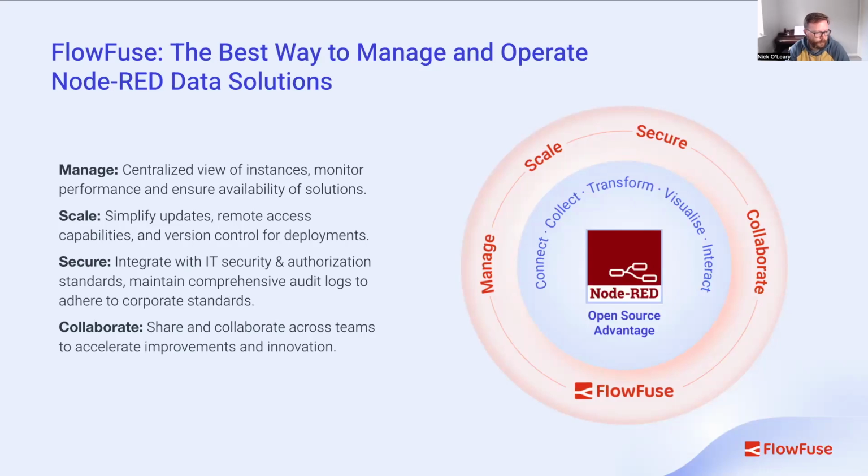A question from Trent Christopher for you, Kurt, possibly. Does Node-RED integrate with special I/O as well as just digital I/O on the rack? And what about remote I/O? He assumes this would have to be handled in CODESYS. Is that one you can speak to? For remote I/O, we would use Modbus remote I/O, like a 750-362 coupler. There are some specialty modules that you can integrate using Modbus. It really depends on the module, but if it's a module that requires one of the libraries, then that's where you would want to use the runtime in conjunction with Node-RED, and then use network variables or MQTT or something to transfer data back and forth.